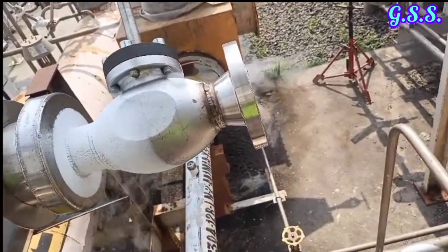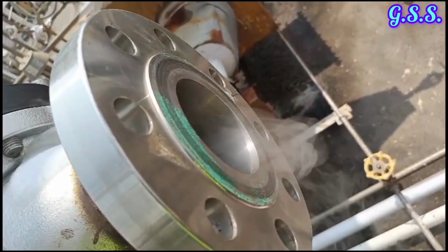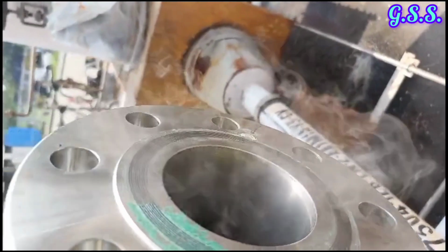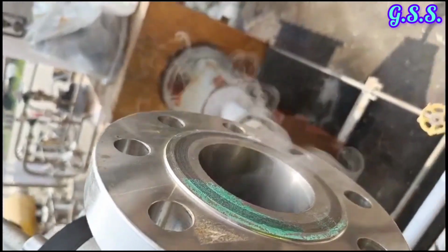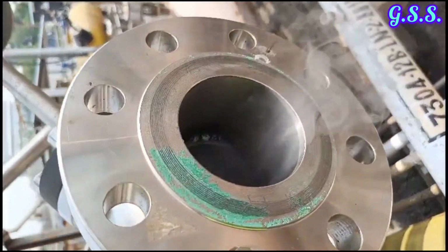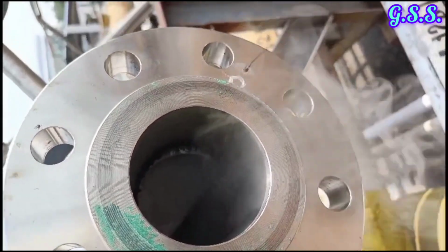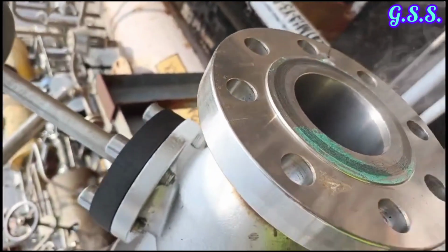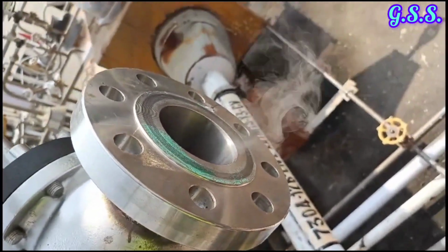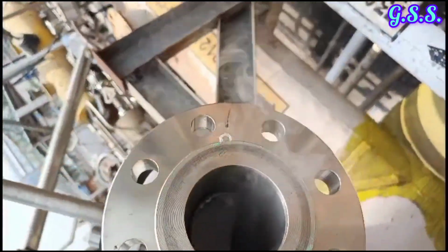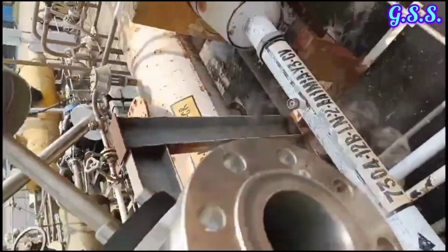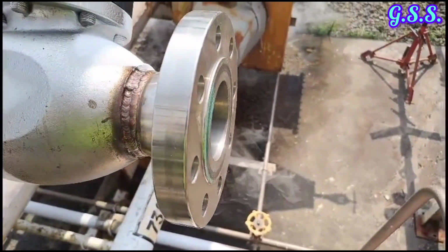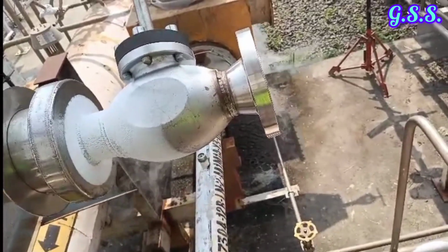You can see the leakage through this stainless steel butt welded globe valve at site at fully closed condition. If the inside fluid is ordinary fluid like air or water, then we can ignore this type of leakage. But if the fluid is hazardous like steam or ammonia, then with this much leakage, it will not be possible to do any maintenance work at downstream of the valve.